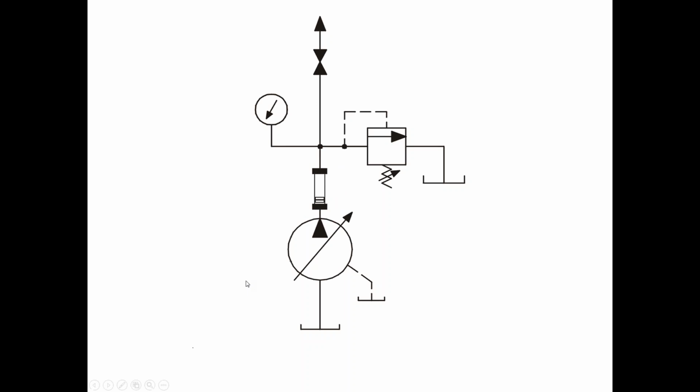If this pump is bad, then it won't be able to deliver flow under pressure. It will be able to deliver flow if it's not under pressure, however. Now let's remember the tolerances in a completely worn out hydraulic pump are much tighter than those of a brand new water pump, for instance, that cannot deliver its flow under load.